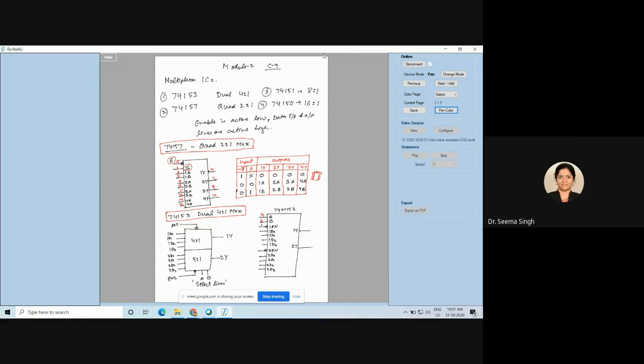Now you will see that all the data inputs and output for the first mux are near to each other. Near to each other means the numbers follow like third, fourth, fifth, sixth, and seventh. And as you know, you will never get to see 8, because 8 and 16 are reserved for VCC and ground. So pin number 9 is here, and correspondingly you will see the input pin numbers as 10, 11, 12, 13, and 14 was your select line.